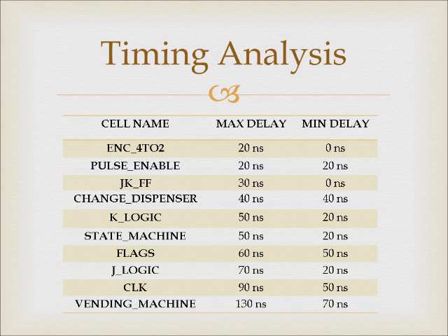A problem was initially encountered when attempting to trigger the flip-flops using the NOR4 as the clock by itself. The clock was faster and not dependent on the J and K logic, meaning that the clock would always trigger before the logic networks would stabilize at the inputs of the flip-flops. As a result, the finite state machine was never able to leave state 0. Therefore, a series of inverters were chained together to delay the clock pulse, allowing the JK logic to produce the proper inputs before the flip-flops were triggered.